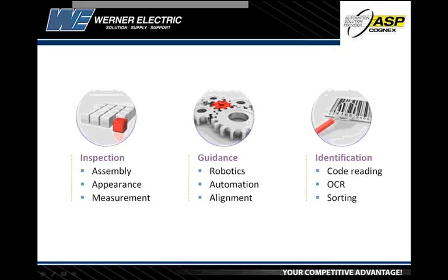So the machine vision system on a robot would be used to find the position of parts that are loose. Say you had a large conveyor with many small products on it that could be located at any position on that conveyor. You can mount a camera over that conveyor looking down and locate the position of the items on the conveyor and then send those locations to the robot, and then the robot can come over and pick them up from wherever they are, even if they're in basically random positions on that conveyor. So it gives eyes to the robot.